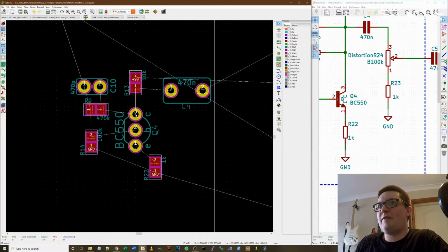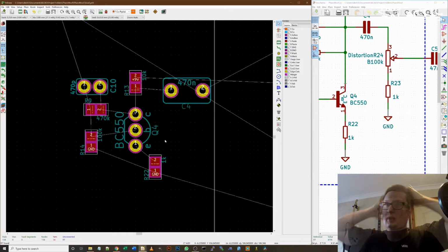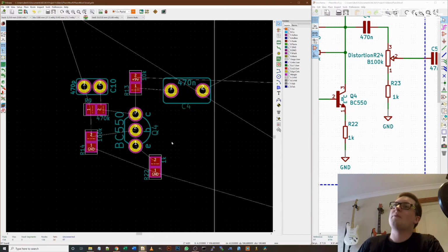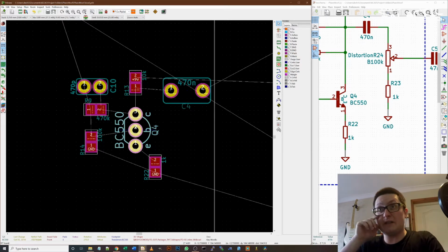So we now have pin 3 collector, pin 1 emitter. If we use our Atlas DCA to test it, this is saying red collector, green base and blue emitter. So it matches what we have on the PCB. That is now correct.